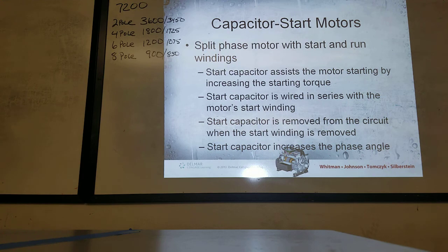Capacitor start motors, split phase motor with start and run windings. Start capacitor assists the motor starting by increasing the starting torque. Start capacitor is wired in series with the motor start winding. Start capacitor is removed from the circuit when the start winding is removed. Okay, so we all know what a start capacitor is? Remember the start capacitor from when we had our hands on? Okay, so that's what they're talking about.